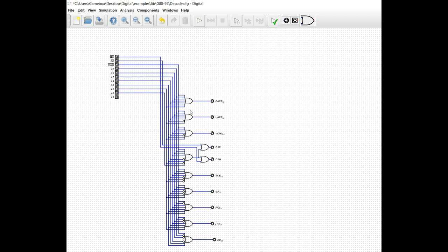And that's part of the reason for the UART pin, in addition to the SIO or the DART chip select, is we are going to incorporate a serial port internal to the CPLD as well, and it's going to be very basic, but we'll cover that in a later video. So for now, we've got our logic laid out. The next thing that we need to do is to do our keyboard decoding. So I'm going to pause the video and I'm going to get that built.